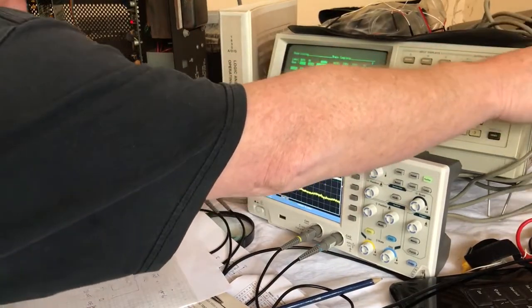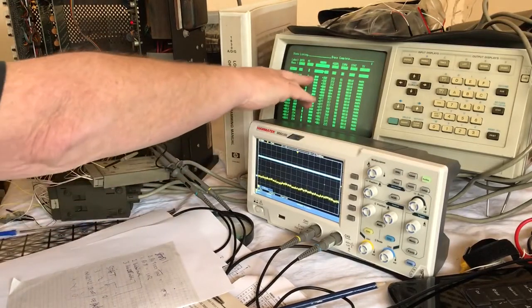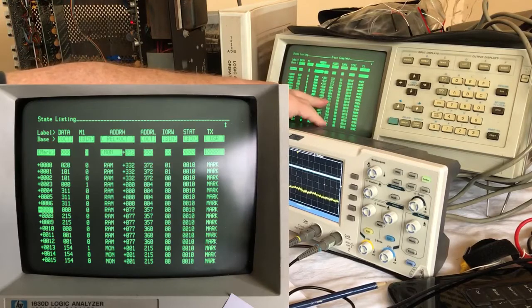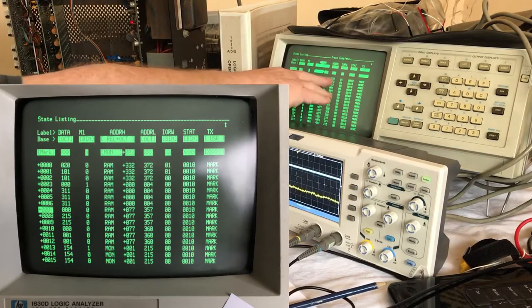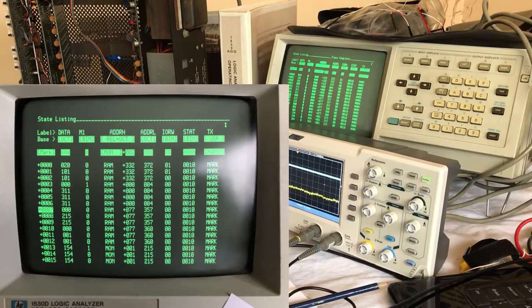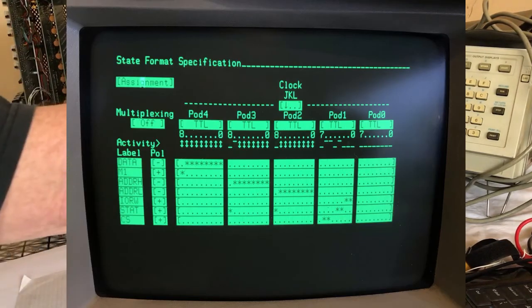The small 8 channel just wasn't enough because I need to be able to select addresses. So what I've done, I've actually set up the split octal so that you can see the octal readouts that will correspond to the front panel addressing, so upper and lowercase. And on the upper range, I've given it some clues about what is in that area. So I've used the labelling function to say whether it's in the monitor or in the RAM. And I've set up a trigger.